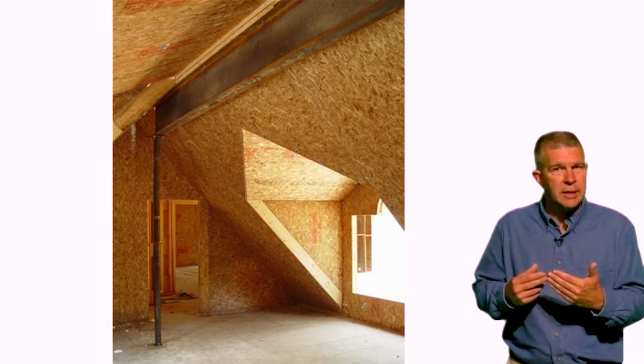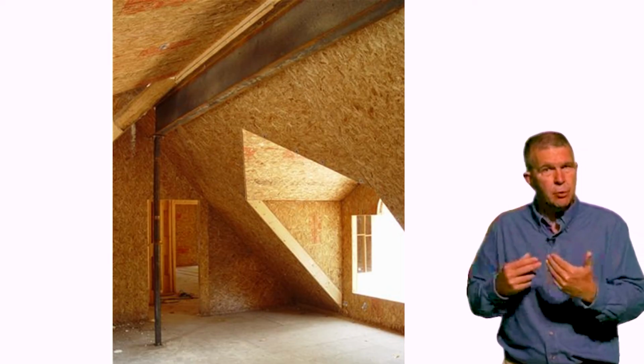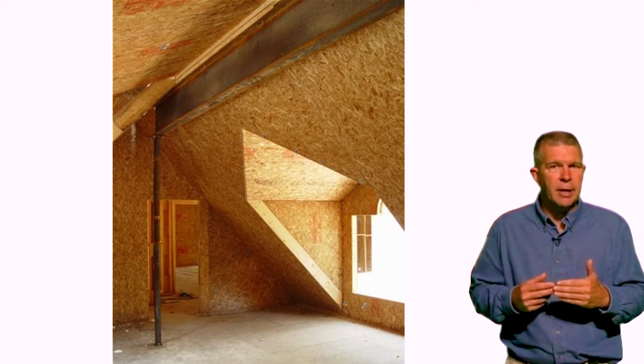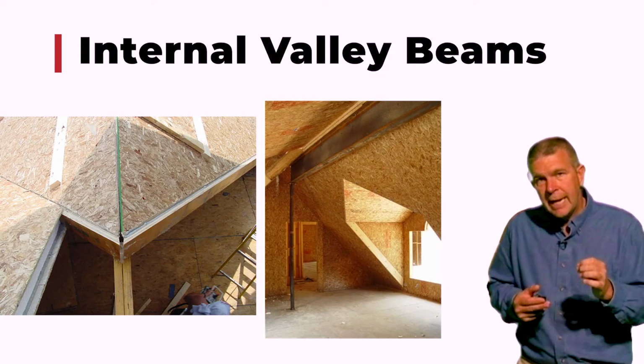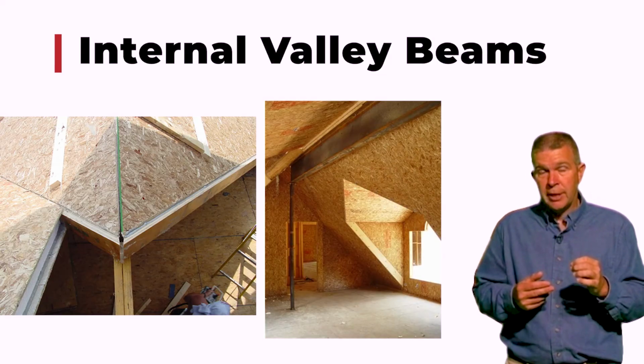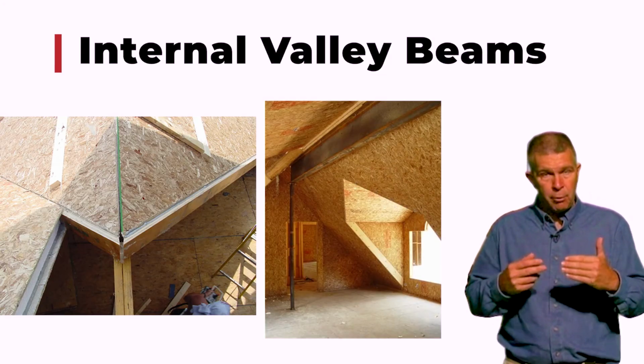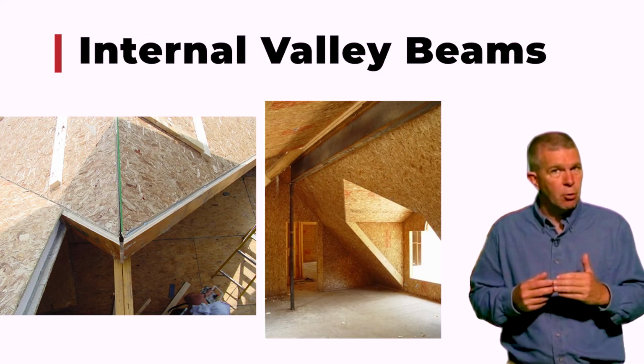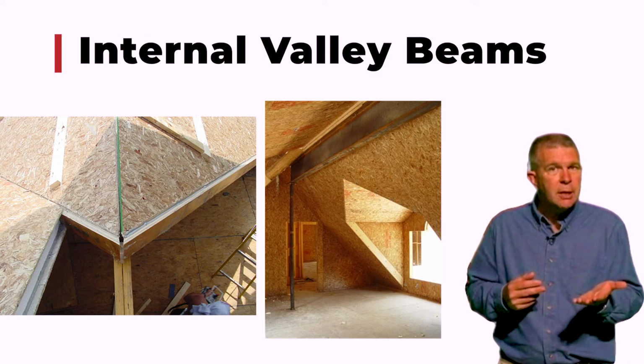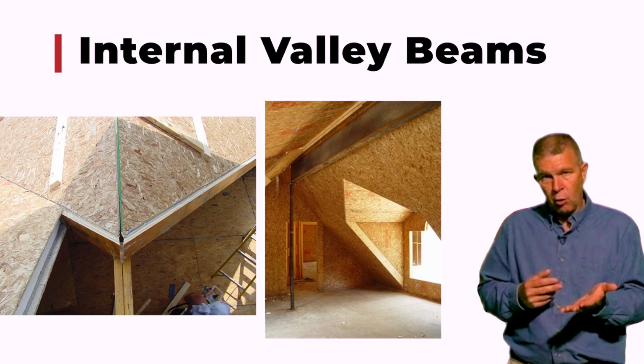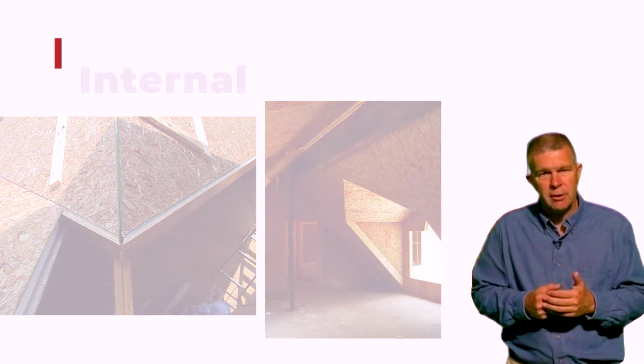It ties very nicely together with the skin to the skin of those two panel planes, and it cleans up very nicely. There's a limitation as to how far we can do this because of the loading applied to the panel. Can't necessarily go great distances. You're much better to support in long distances with that beam underneath.